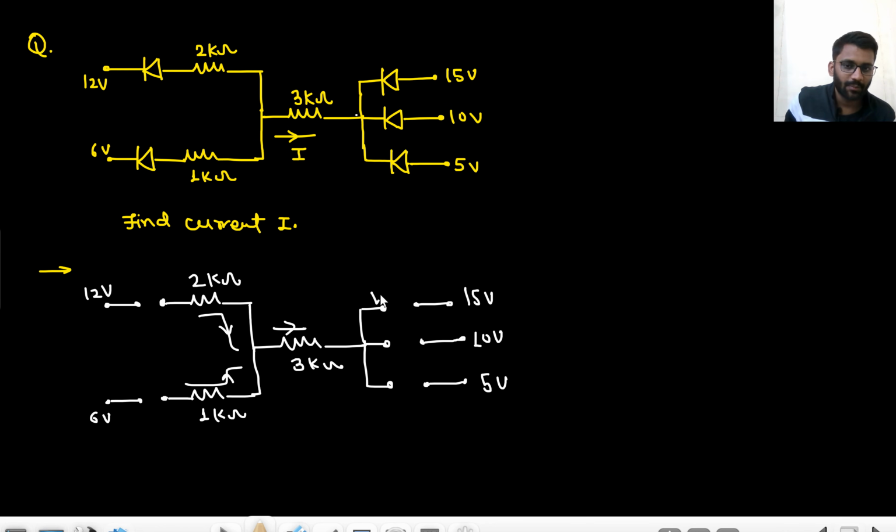So you have to consider some potential. Let's just assume this is having V potential, the same potential will go here, the same potential will go here. Now there is no current in these branches, 0 ampere, 0 ampere, 0 ampere. So this same potential will be varying here. Now you have to compare. You can take any value of V. Let V equal 1 volt.